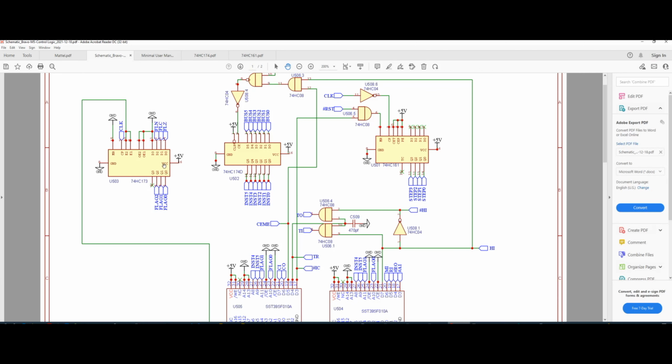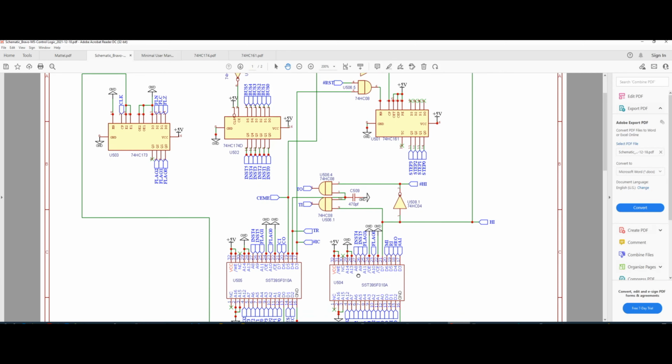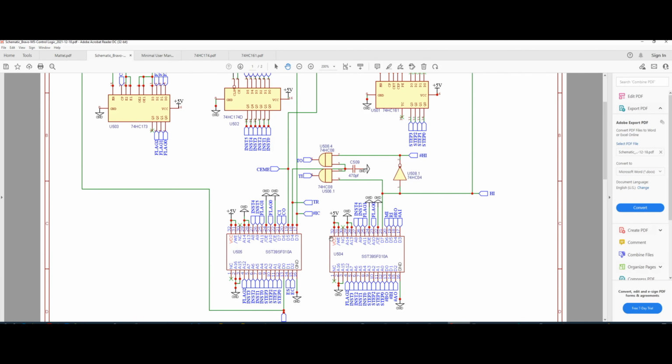Now, the output side of all these 3 sections, as you can see, is connected directly to the address lines of our flash memories. And if you look at it carefully, you see that, for example, the address line A0 is actually connected to step 0. So that step 0 is coming to the least significant bit on the address line of our flash memories, and it's going to continue to instructions, and then after instructions we're going to have the flags.